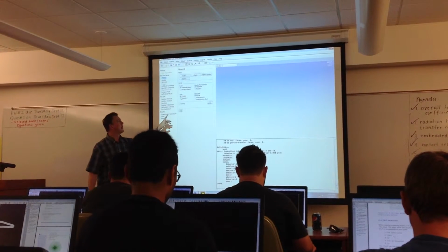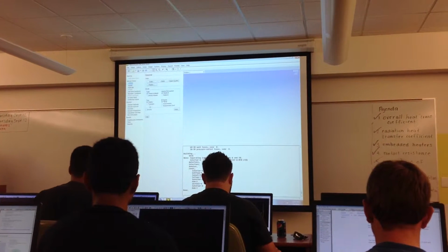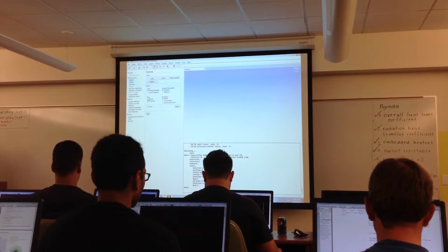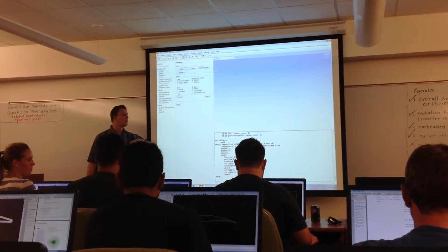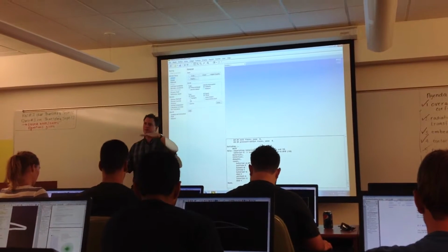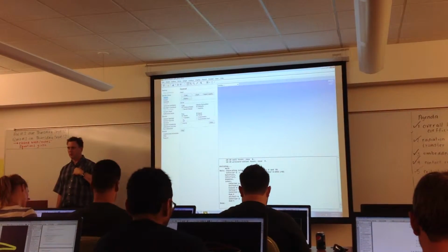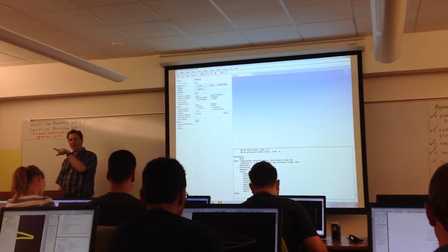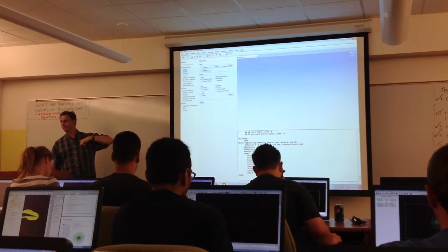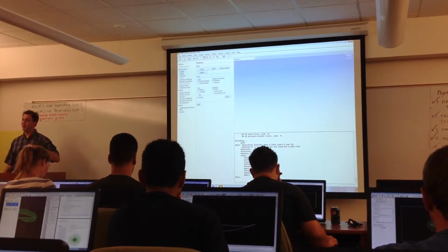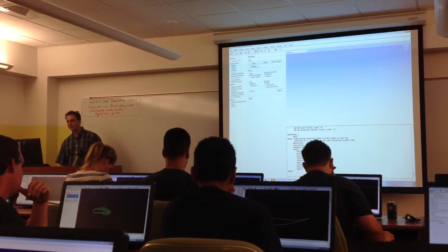So actually, for the projects, I don't think we've ever done this before in the class. I'm going to recommend that we run transient solutions. I'm going to start off with your study today, but I want you guys to run transient solutions for your final answers for your designs, and actually get a time-dependent solution, and essentially take the average. You're going to graph out what the lift and drag is versus time, and give me an average number, because that'll be closer to reality. Some of you will have a lot more unsteadiness than others, depends on the specific design. So for now, I'm picking steady.